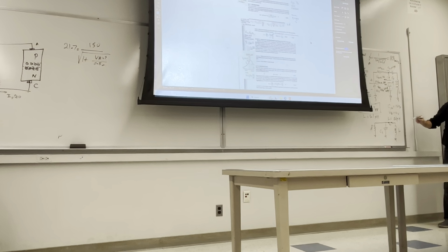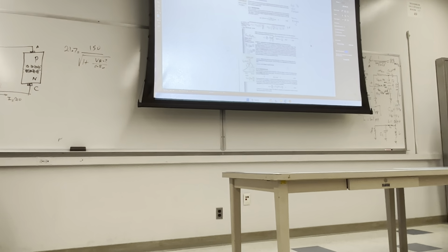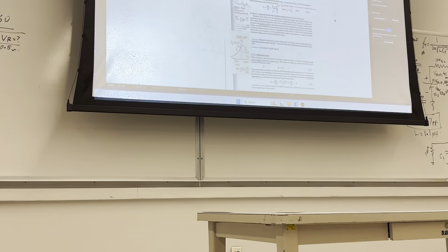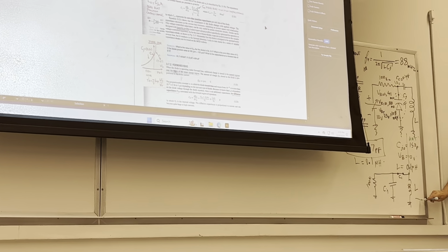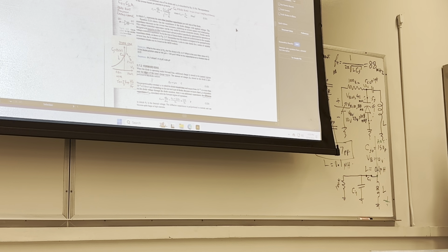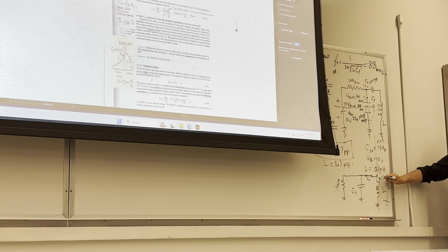If you take one of those poles we were talking about and you put it in here, an antenna, you put an antenna there. An antenna at its bottom with respect to the ground looks like a Thevenin voltage source with some kind of resistance, typically 50 ohm, that feeds this. This is the incoming voltage, the power converted to voltage. It is known as the power available from the antenna.